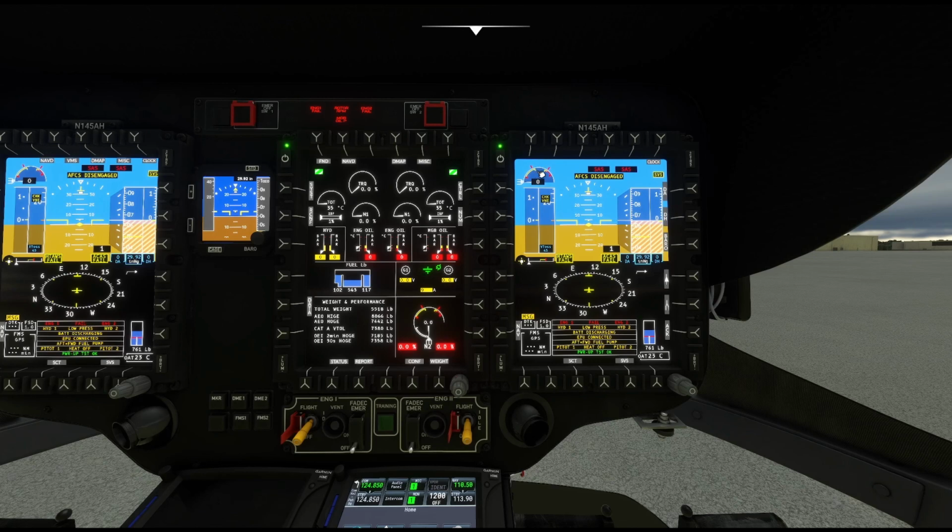All right, so this tells us what percentage of 383 the rotor system is spinning at. Then our N2 for each engine is converted to percentage as well, and these are mechanically linked with a Sprag clutch. If the rotor starts turning faster than these, the Sprag clutch will disengage and allow the rotor system to continue turning at a higher speed than the engines.